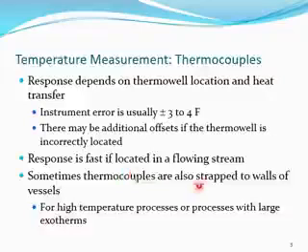Sometimes thermocouples are also strapped to the wall of the tank. Of course, it is installed mostly if we want to measure the temperature of a storage tank. The thermocouple should be installed right in the place. For example, if it is crude oil, it should be installed right below the level, or the set point of the level.